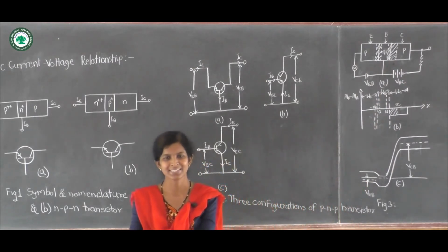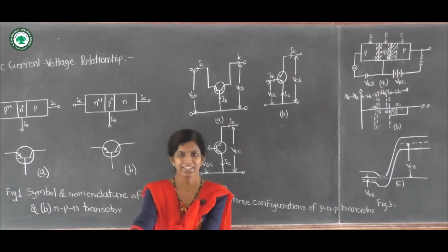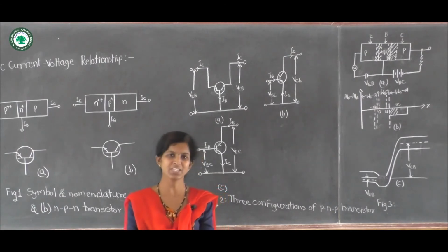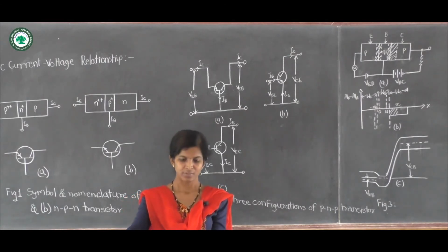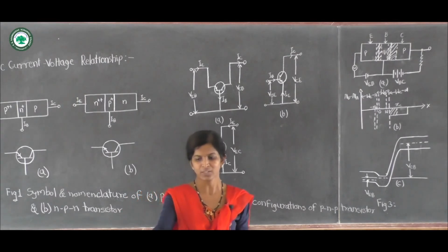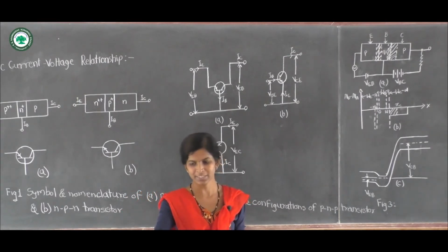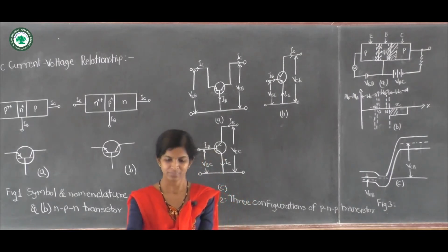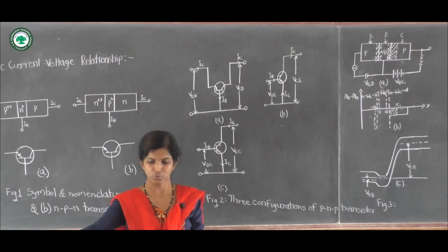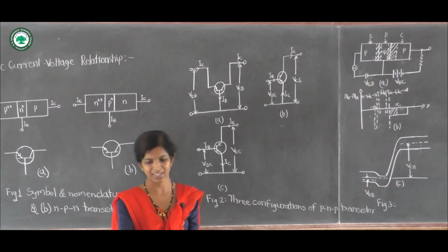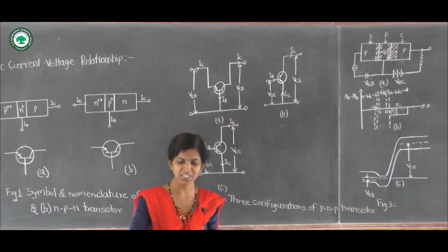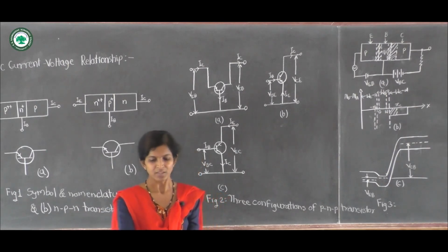The static characteristic can be readily derived from PN junction theory. To illustrate the major property of the transistor, we assume that the current voltage relationship of the emitter and collector junction is given by the ideal diode equation. That is, the effects due to surface recombination and generation, the series resistance and high level injection are neglected. So these effects can be considered later.